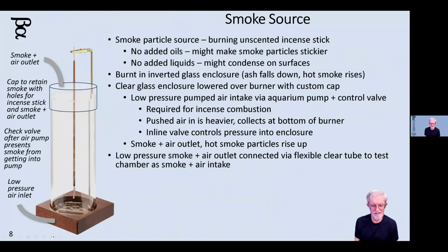Here's my smoke generator. It's an incense burner, but I put a cap on the top of it, and I drilled a little hole through the cap for the air line to come out, and I drilled a little hole in the top just big enough to let the incense rod go down into the chamber, and then it burns from the bottom up, and the ash falls onto the bottom of the glass cylinder. I had to actually learn how to drill a hole through glass in order to get the hose in the bottom so I could pump the air in to get the smoke plus air to go out the top.